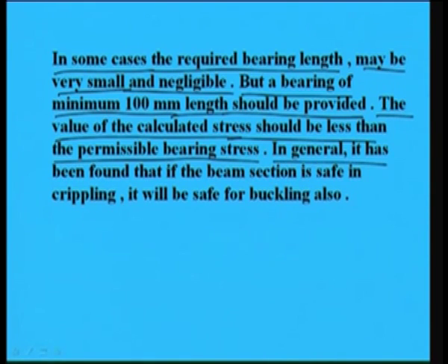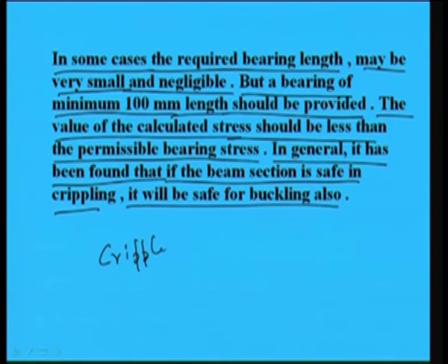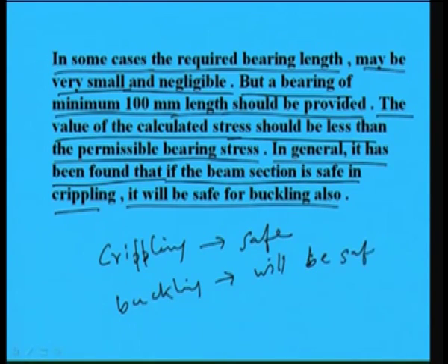So, in general it has been found that if the beam section is safe in crippling, it will be safe for buckling, right. When we are checking the crippling stresses, if it is safe for crippling, then buckling also will be safe in general, but we cannot assume it for all cases, we have to check.